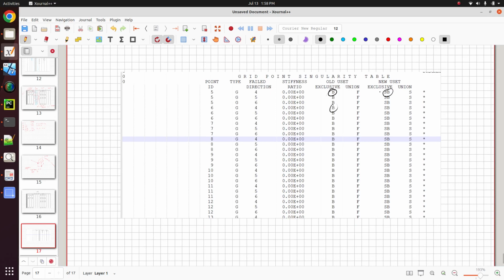So what's happened here is that internally, these degrees of freedom were free before. And if you remember a few moments ago, we manually constrained them. We added SPCs, single point constraints, all equal to 0, so the thetas were all equal to 0. We manually did this before.